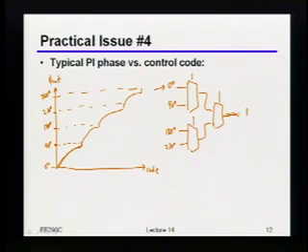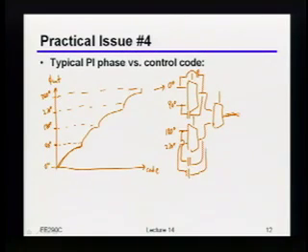Is it because of Miller coupling or something? Ah, there we go. It's the feed forward. So the really annoying thing about this is that, remember, I've always got these darn Miller caps, right? And, okay, I ran out of space, so I'll do it down over here. I've always got these darn Miller caps between the inputs and the outputs, right? And so what's going to happen is that if I choose a different clock phase, the impact of that Miller cap is going to be different, right?